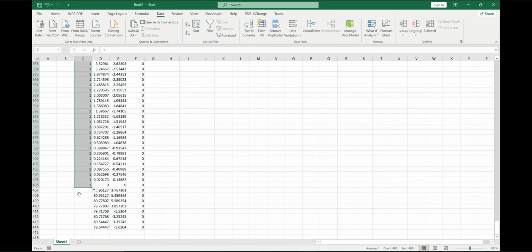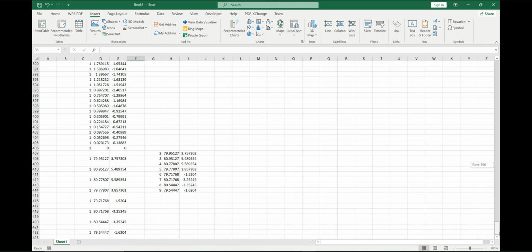We want flaps as points. There are 2 possible approaches to do this. The first and most common method is to leave a blank line or cell between consecutive points. By separating the points this way, SpaceClaim treats each one as an individual entity and imports it as a separate vertex. The second method is to assign a different curve ID to every point.